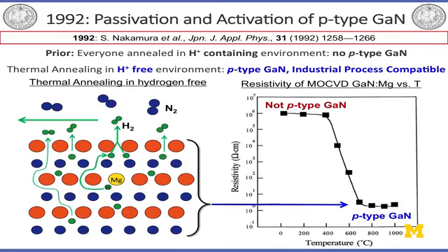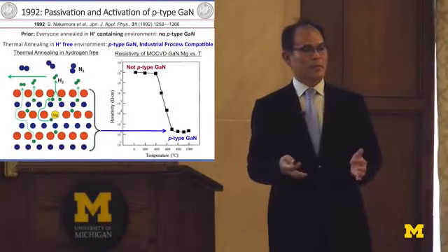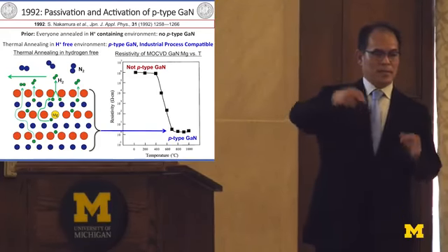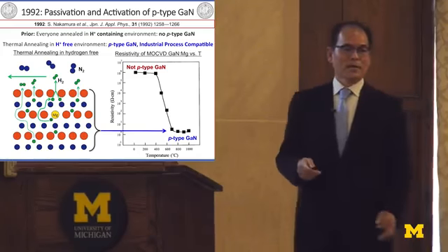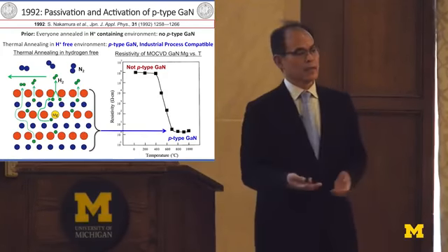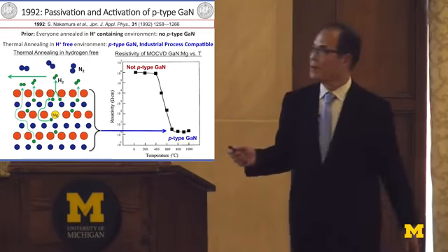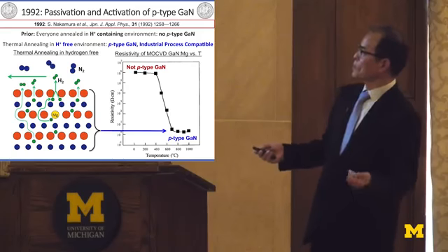So first, after the invention of 2-flow MOCVD, I had to develop P-type gallium nitride, the P-type top layer. In 1989, Professor Akasaki and Amano had already developed P-type gallium nitride using electron beam irradiation treatment. But the problem with electron irradiation treatment is that they have to scan the electron beam over a 2-inch substrate. It takes almost forever. And also, the biggest problem was that they couldn't understand the mechanism, why they got P-type gallium nitride by electron beam irradiation.